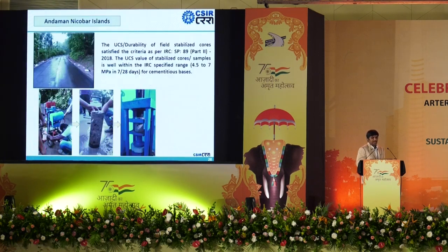Similarly, we evaluated some roads in the Andaman and Nicobar Islands, where there is a lot of shortage of aggregates. So in such locations, it's a very useful technology. With the same material, you can reuse it, because otherwise you need to get aggregates from the mainland. So it's very difficult, a very costly business. In such locations, you can reuse the same material and compact it.